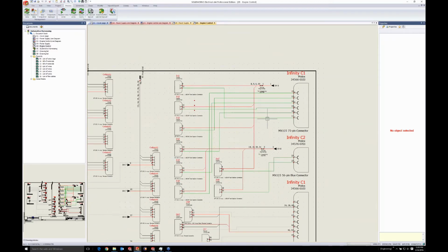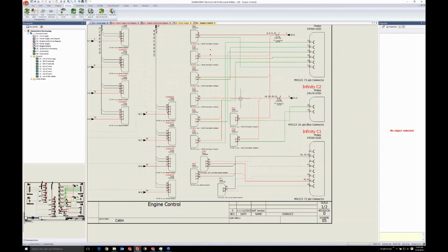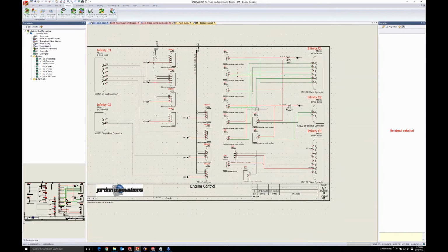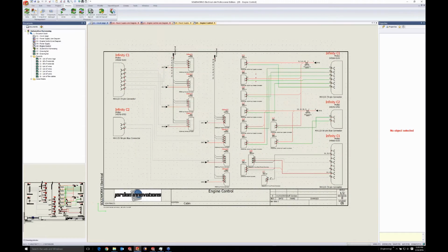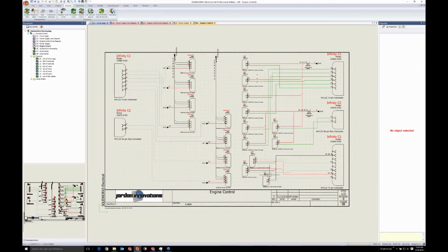Select the wire style that represents the individual wire I'm using. This is really handy. I basically separated out coil packs, injectors, and sensors, just a little representative version of some of the ways to use our connector tool in our multi-line. This really helps because we need point-to-point wiring information in order to route these wires.